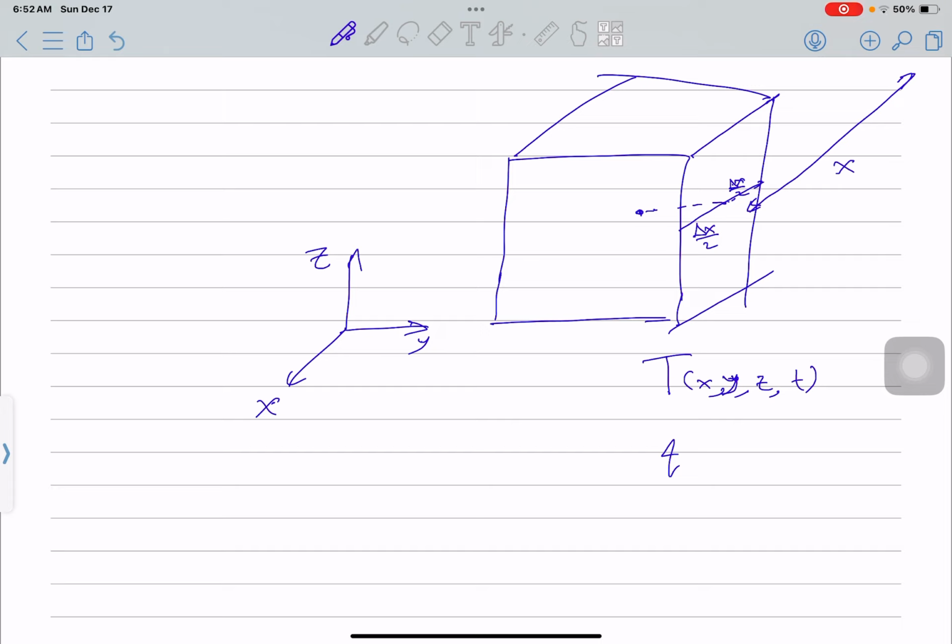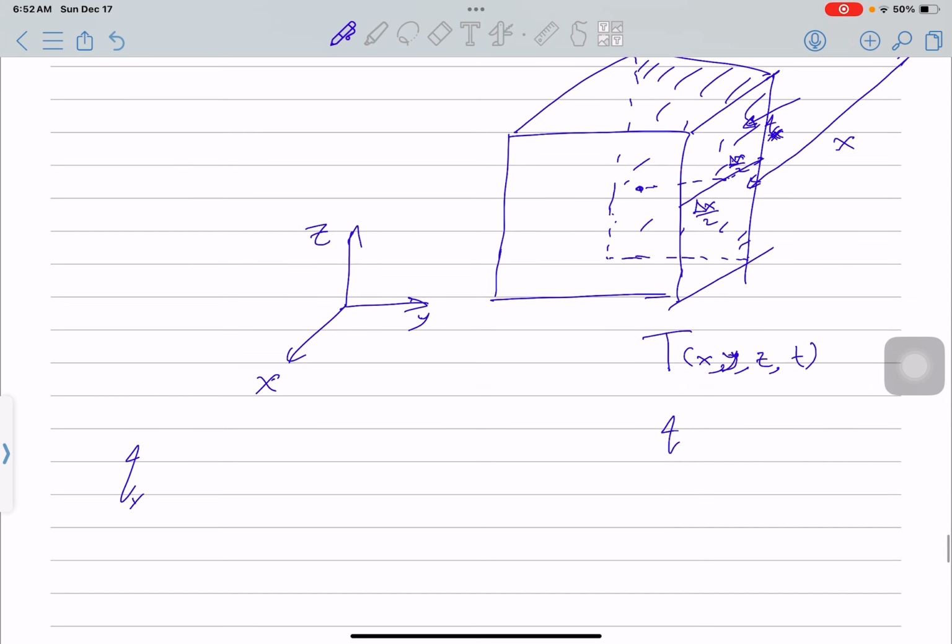and we also have a flux field that we introduced in the first part. If we have this plane that is behind our cube, we need to find the energy that goes into it. We define Qx as being the heat that is flowing in the x direction. What is Qx equal to? We know that Qx at this point, which is at the middle of the cube, equals negative k A partial T by partial x.